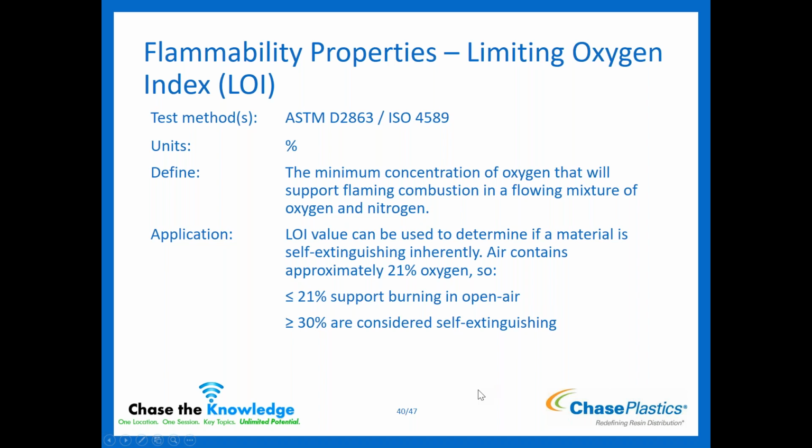Now we'll start to talk about flammability a little bit. Limiting oxygen index, LOI. This is essentially the amount of oxygen that's going to be needed to support flaming combustion in a flowing mixture of oxygen and nitrogen. So how much oxygen needs to be present for this material to continue to burn if lit on fire.